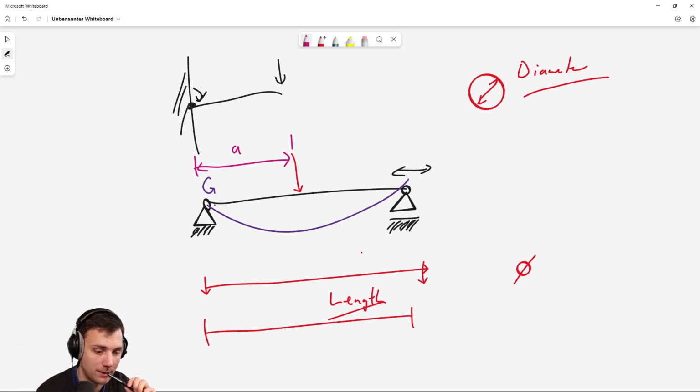And as my boss already told me a couple of times, and it's rather important that you know that as well, we only believe what we understand and what we can see. So it's always important to have your finite element modeling checked by a hand calc. And so I prepared something in advance. You can find the analytical equations on different sites in the internet. So this is rather easy to find and prepare it in advance.